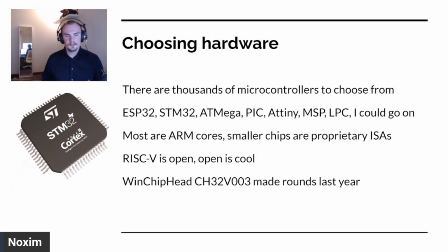So when developing embedded stuff, really the core of your system is going to be the microcontroller. A microcontroller is like your processor and your motherboard and I/O in one small thing, one single chip. And you really have tons of choices. There's really popular microcontroller brands. You got ESP32s, STM32s, ATmega, which is used in the Arduino, for example. And just tons. There's like 101 manufacturers, and all of them have 101 different product lines. So there's a lot of options.